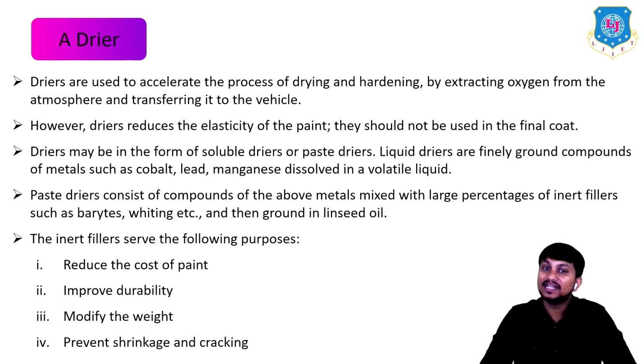And they are then ground into the linseed oil. The inert fillers serve various purposes: they reduce the cost of paint, improve durability, modify the weight of the paint, and also prevent shrinkage and cracking problems. So these are the various purposes why we use this type of filler.